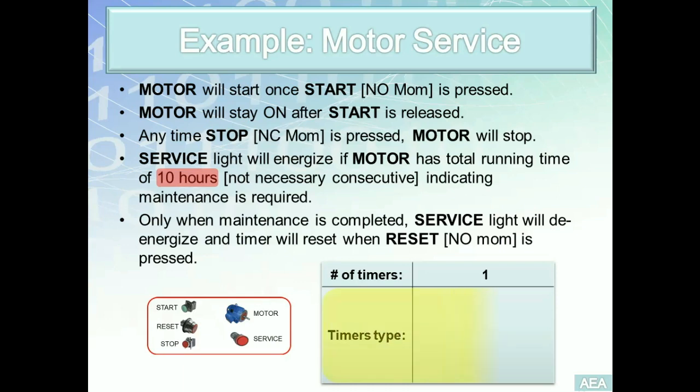The second thing is what's the best timer type we can go with to fulfill this requirement. So one more time, we have 3 timers, TON, TOF, and RTO, and to decide which timer is easiest to go with, we need to go with the requirement that involves the timer delay values, and we need to look at the key terms, and this is going to help us to decide TON, TOF, or RTO.